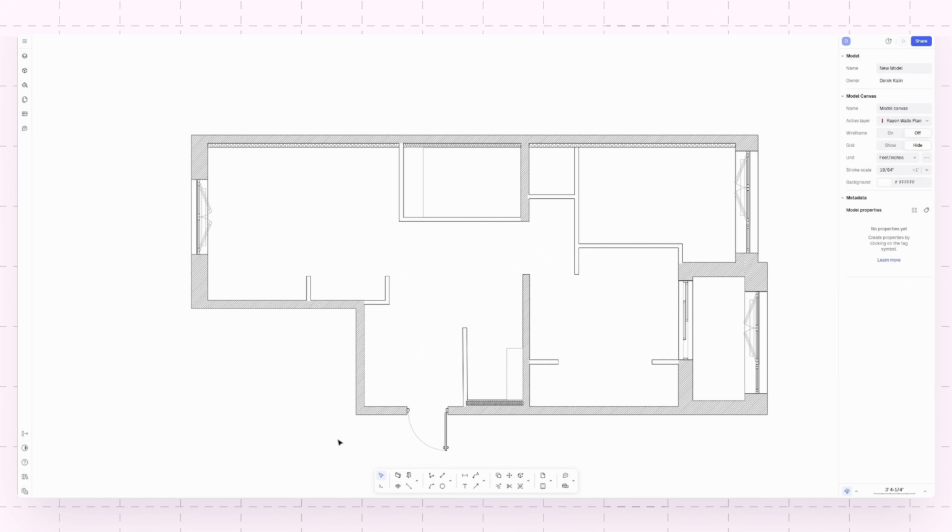Now that we have all of the openings and all the walls that we want, let's talk about the zoning tool. The zoning tool is right here at the bottom under the door and the opening tool. For making zones, you're going to want to use the zone tool and the zone divider tool. The zone divider tool will let you separate rooms where there isn't a wall between them. If you use the zoning tool, as you can see here, it's trying to make everything in blue one big zone.